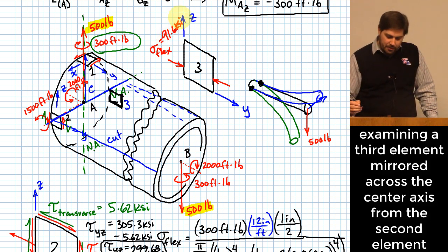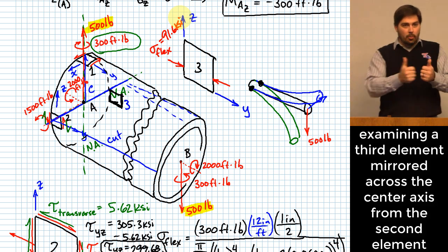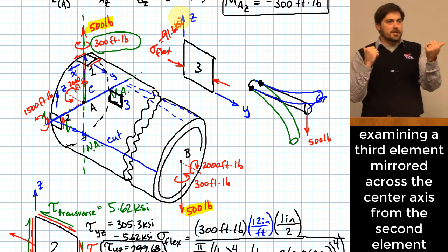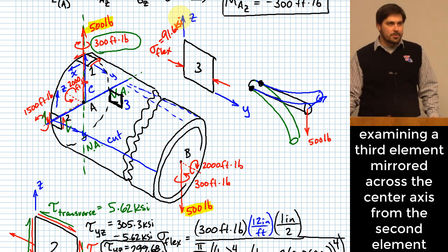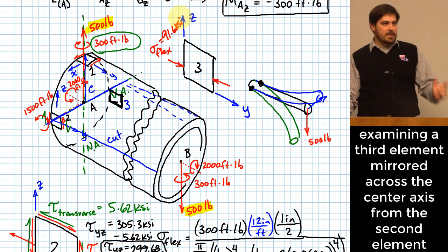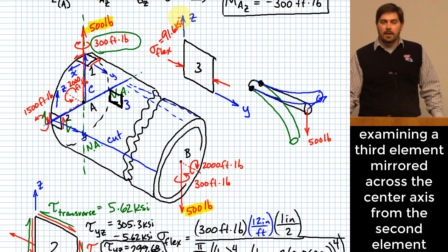Okay. Another standard a lot of people use for this is to always draw the arrows in a tensile direction, and then you use negative values to refer to a compressive stress, right? But you don't want to double up on that because then it becomes ambiguous, right? You could have a double negative there. All right. What about shearing?